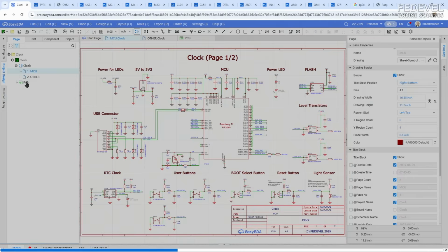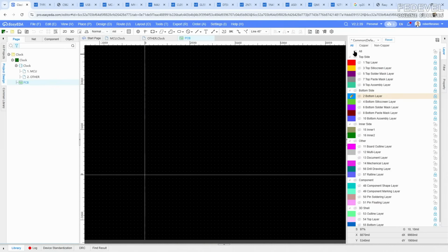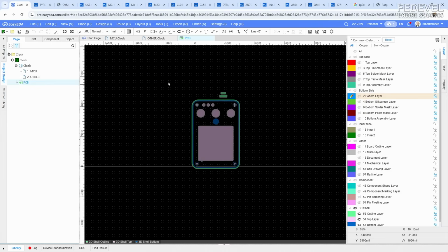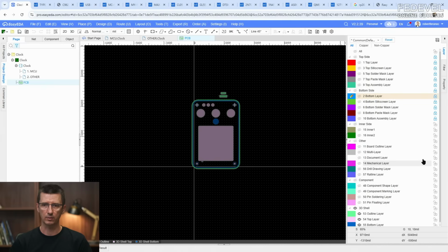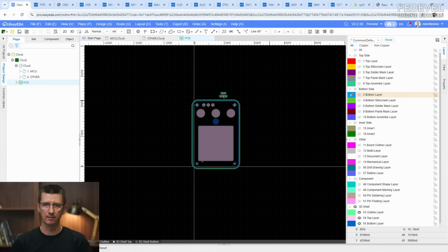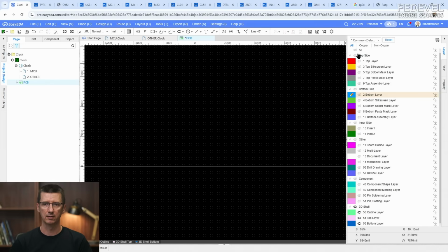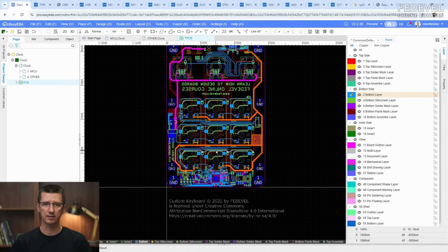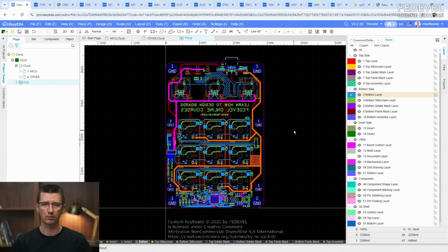Let's go to PCB. And first we are going to delete all 3D stuff. That's the enclosure, the box for keyboard. But it looks like these layers, they are locked. So we need to unlock everything first. Now let's try to select them. Okay, press delete. Enable all the layers. And we are going to keep this, the components around the microcontroller and microcontroller itself.